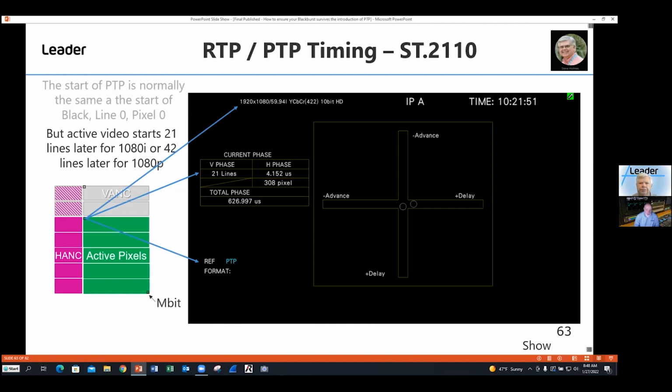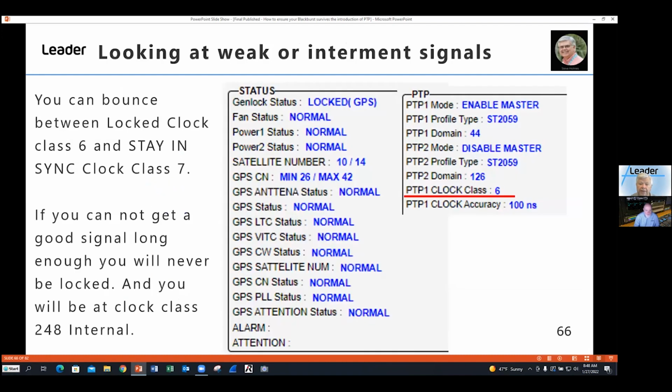So Steve, earlier in this webinar, you described the best master clock algorithm and how it ensures a resilient PTP reference. What happens to the PTP reference if the GPS reference source is unreliable? It's a great question, Kevin. And this can happen a lot, especially with people with trucks going out to a venue, because in some cases, the trucks end up underneath of the stadium or underneath some other awning where you can't get GPS.